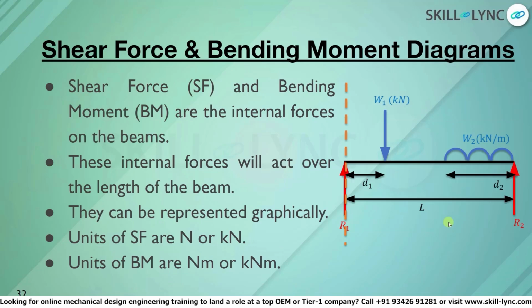Now, let us look at shear force and bending moment diagrams. Shear force and bending moment are internal forces on the beam. These internal forces act over the entire length of the beam. They can be graphically represented also. These graphical representations are called shear force diagrams, SFD, and bending moment diagrams, BMD.